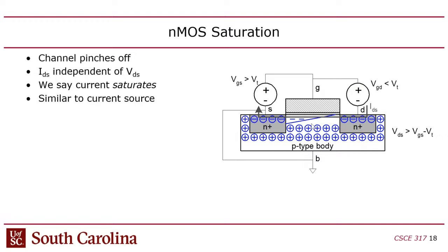So if the transistor has a load, like you have a gate, for instance, and that gate is connected to a bunch of other gates, it has a fan out, right? Or a long wire, for instance, or a pin that goes off chip, for instance, connecting to an SPI bus. And so you've got a lot of metal. You've got the gate driving a lot of metal, which means a lot of capacitance. If you have a bigger transistor here, if your width is bigger, if you have a wider transistor, then you can get more current when it saturates, and that will cause the load capacitors, whoever you're trying to drive, to charge or discharge faster.